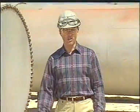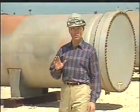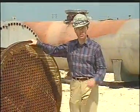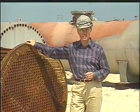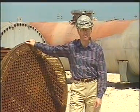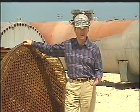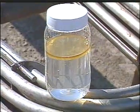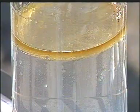Leaks are another important maintenance concern. Whenever exchangers are down for cleaning, they're almost always tested for leaks. But before dismantling the exchanger, there are some preliminary tests you can perform. One simple way to test for leakage is to take a sample of the lower pressure fluid and check it for contamination. If the fluids are very different in appearance, like oil and water, just looking at the sample should tell you if there's a leak. This sample, for example, has a small amount of oil in the water line, a sure sign of a leak.